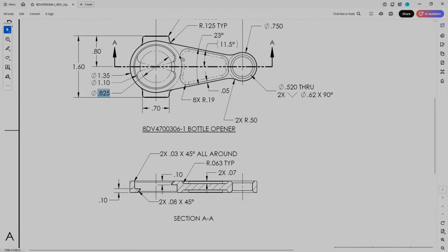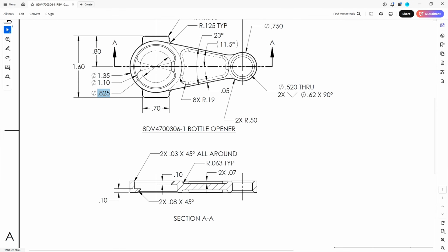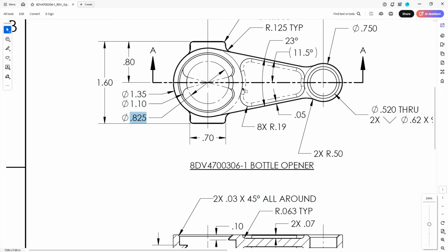and it is this blunt triangular shape. As you notice on the drawing, there's no dimension for this top arc. That's because it's the same diameter as the outside of our part. Okay, so this arc is 1 inch 350 thousandths, and it's a similar case on the other end. So that's going to dictate the width of our part along with the radiuses and the angles.